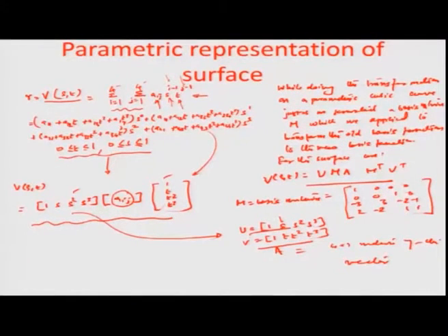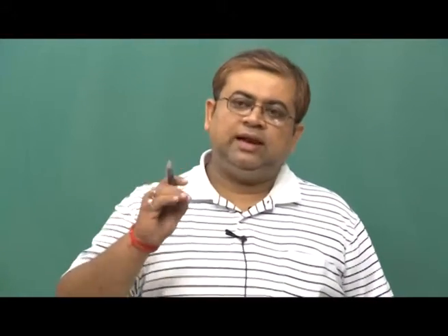So, this is how the data structure would then be created for a surface, because now if we send in the various values of the s's and t's in terms of fractions. For example, remember when we were plotting the Hermitian curve, we talked about the various values of t starting from 0, 1/4, half, 3/4, 1, and so on. So we do the same for t and the same for s, and so there are at least 25 different combinations of these values across which you could find an array of points.